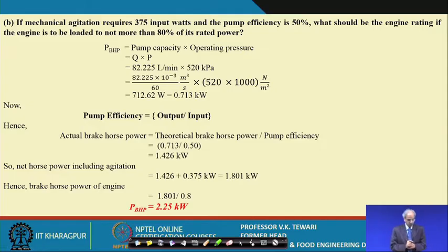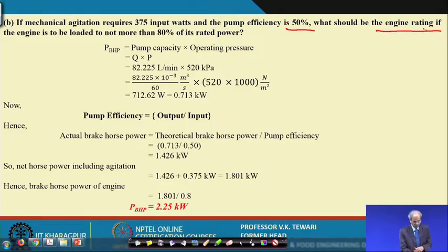Second aspect, mechanical agitation requires 375 input watts and the pump efficiency is 50%. What should be the engine rating if the engine is to be loaded not more than 80% of its rated power?